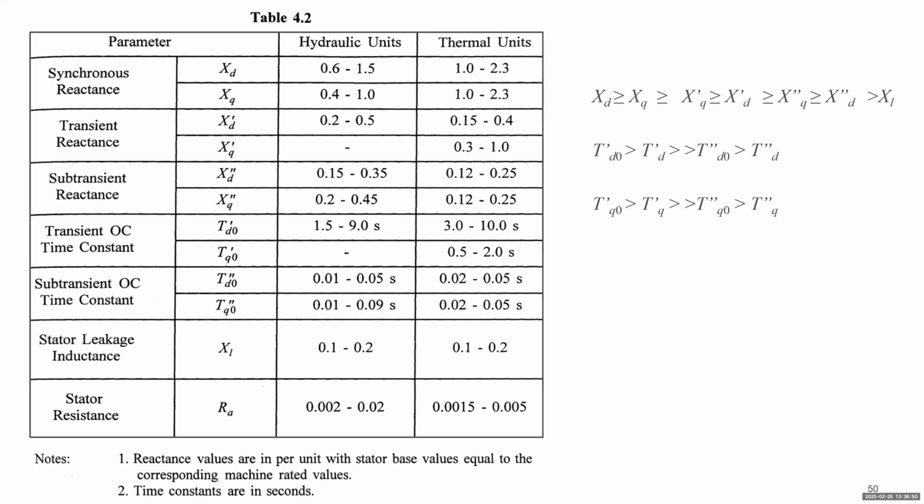Also, for instance, you have a power system model where every generator is a thermal unit, which is a round rotor generator, but you also want to assume one region to be a hydro power plant. You definitely cannot use a thermal unit; you need to change it to a hydraulic unit. So when you change to a hydraulic unit, you can use this table to create another set of data, because the D axis and Q axis are not fully symmetric anymore.